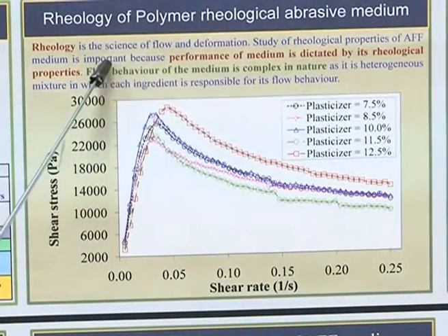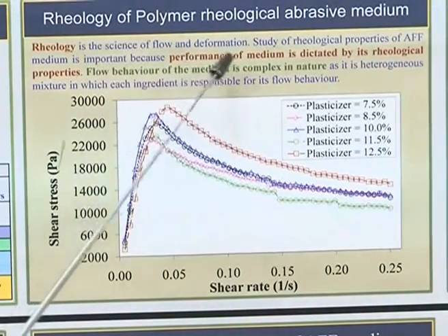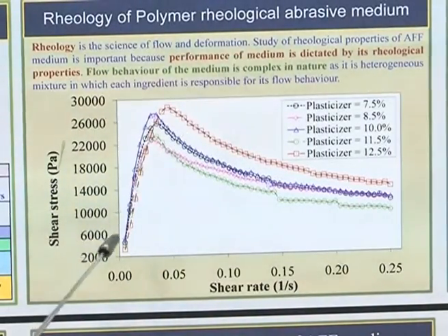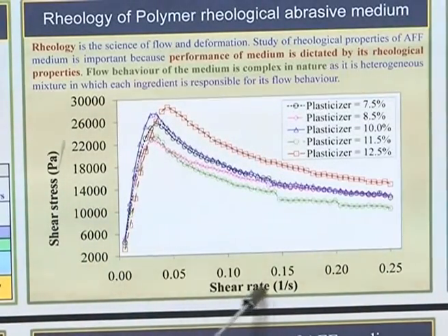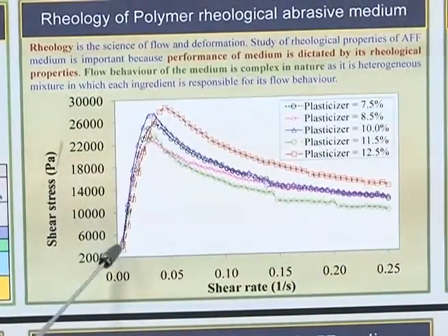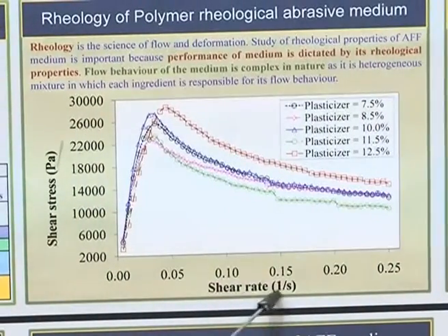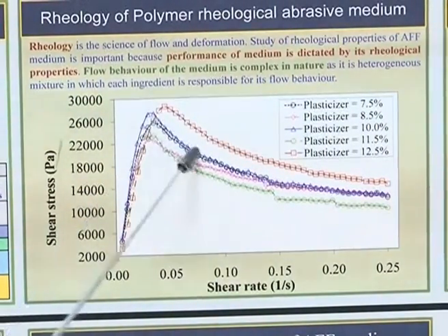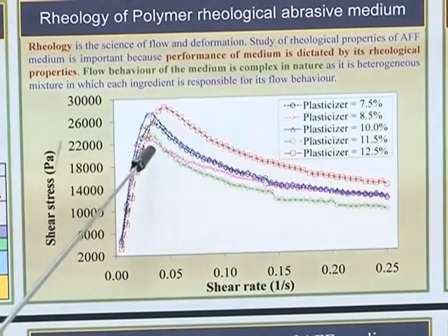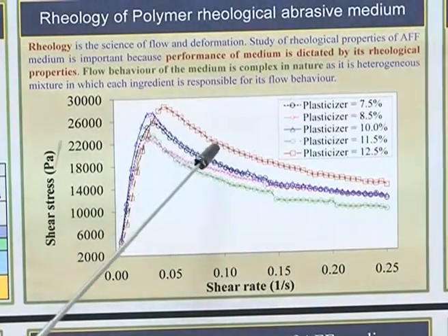The rheology is nothing but the science of flow and deformation, and this is the basic flow test, wherein you are seeing the shear rate versus the shear stress. You can see as the shear rate increases, the shear stress increases steeply and gradually falls down. This is the basic curve of the viscoelastic medium.